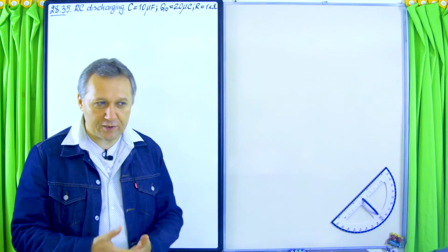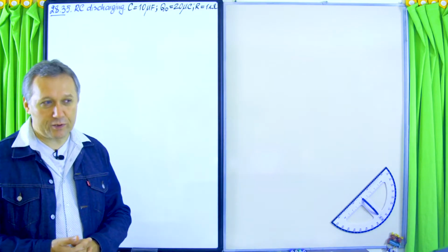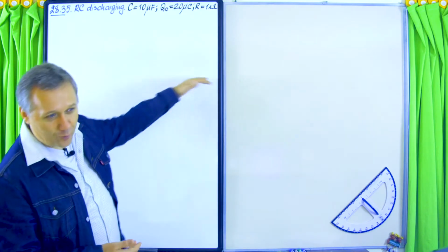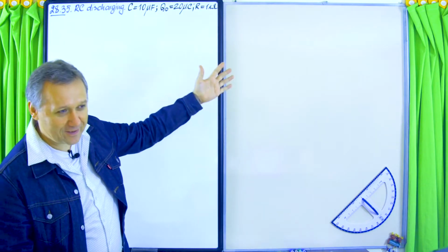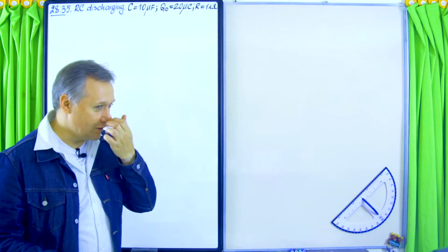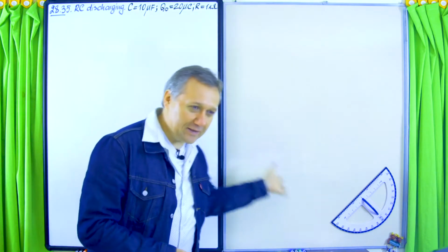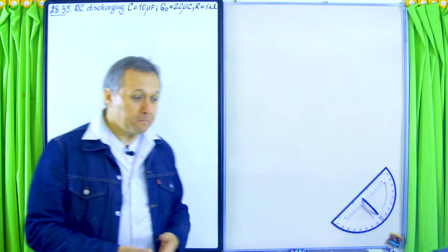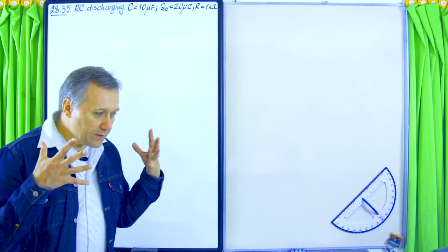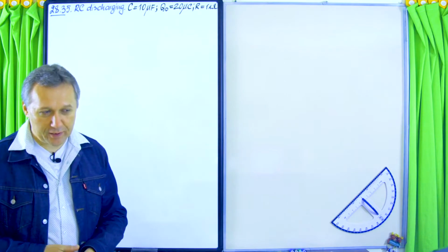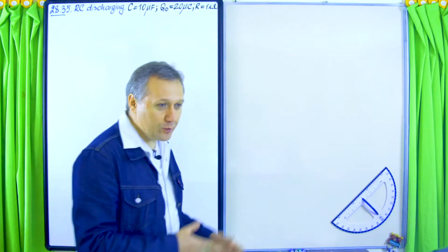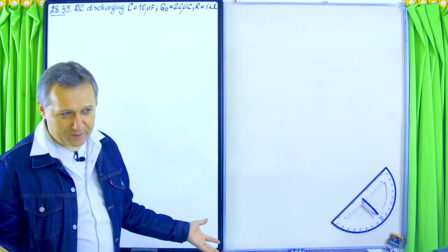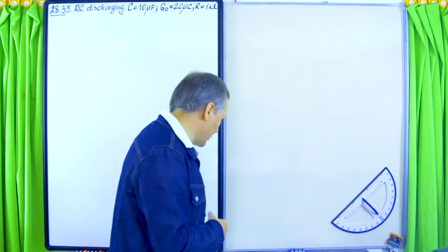How charge changes in the capacitor with time is of course different, because in the first situation charge is growing, but in the discharging situation it decays exponentially. And then you can easily get the potential differences across elements using either Ohm's law or the definition of capacitance, as I showed you yesterday.